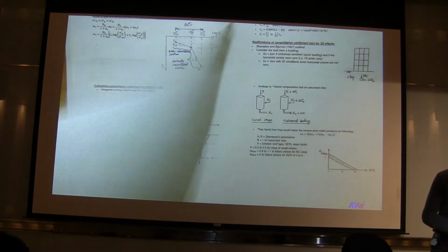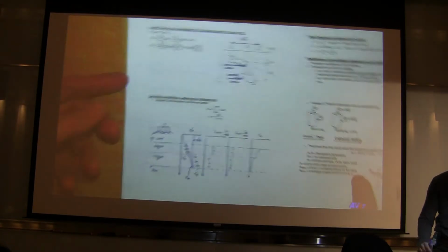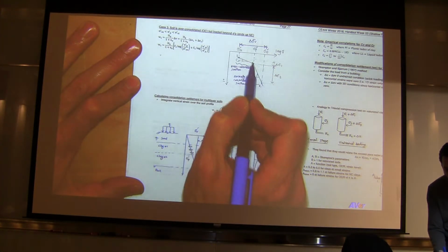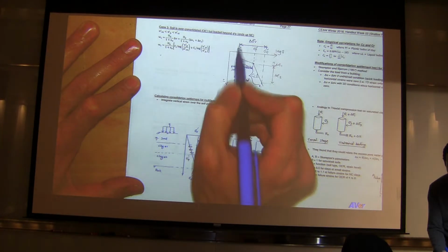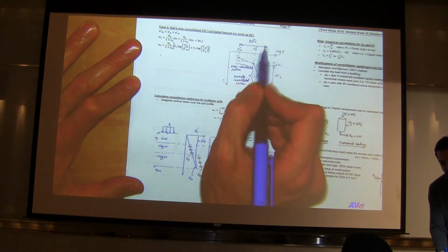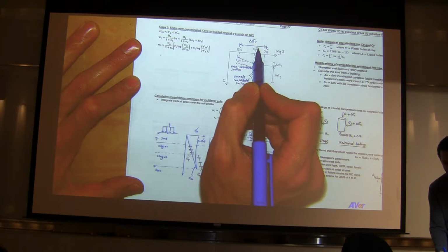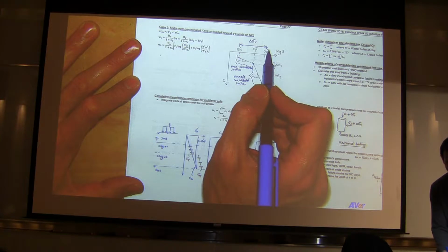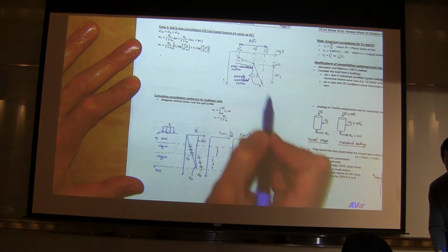And you can probably guess what case 3 is. Case 3 is, again, that's your OC curve, this is the NC curve. You start before sigma prime p, but your load is large enough that you pass the sigma prime p point. So you start OC, you end NC. Because you start on the OC part, you end on the NC part.